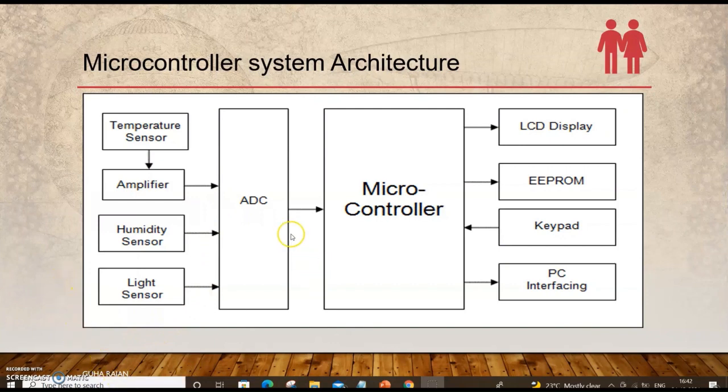So that is the analog signal, and that needs to be converted into a digital signal, and digital signals are fed into the microcontroller device, so that the data gets displayed in the LED display, or it can be sent to the printer. Again, you will have a program which calculates all the weight and sends the data to the display.